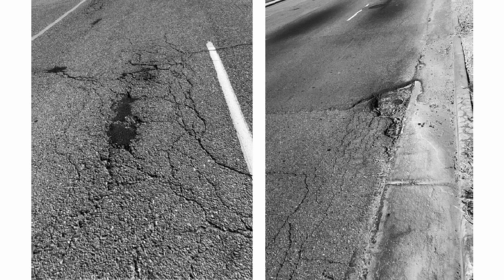It is very difficult to identify stripping as it starts at the bottom of the asphalt layer due to the presence of moisture, and when it reaches the surface, it accompanies other forms of distress, such as rutting, shoving, corrugations, raveling, or cracking. Coring is the only option to identify stripping. The figure shows two candidate pavements with stripping. Full-depth coring is required to confirm these are stripping.